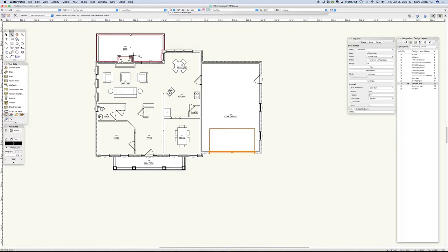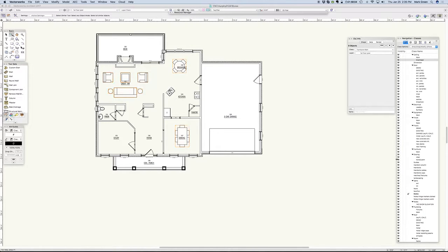And I'm just checking, I'm clicking on something, so let's do furniture first. I'll click on that. I'm seeing that all of the furniture looks like it's selected, and then once I turn off that class, I'd make a quick scan again to see that there's nothing else that should have been selected.